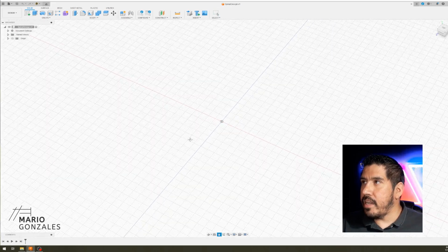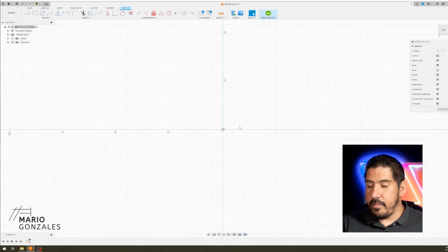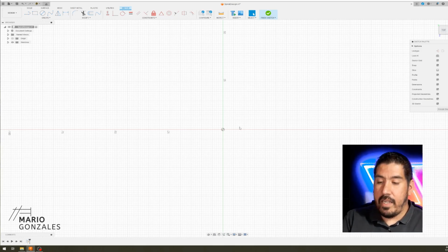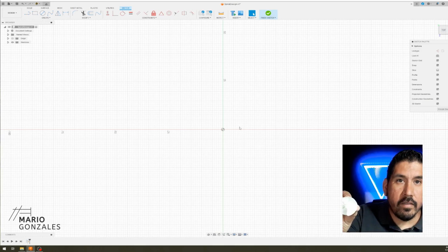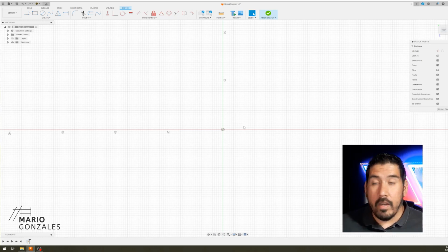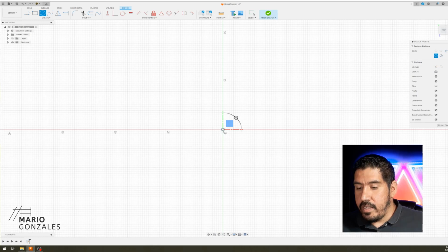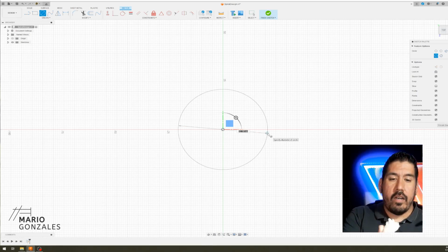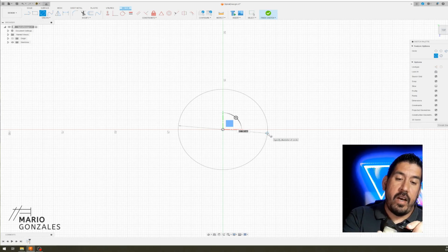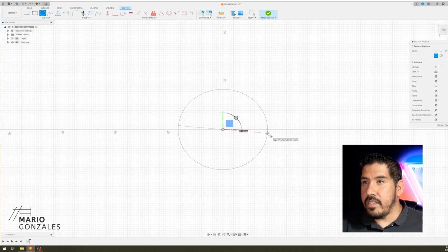is I'm going to create a sketch. And if we look at this spiral design, I'll take the center out. It has 6 sides. Now, when we make it, I'll put however many spirals we want, but I think I'll stick with the number 6 for now. So let me see this design. If I measure it with my calipers right here, put it together, it's about 1 3/4 inches. So let's make 1 3/4 inches in here.